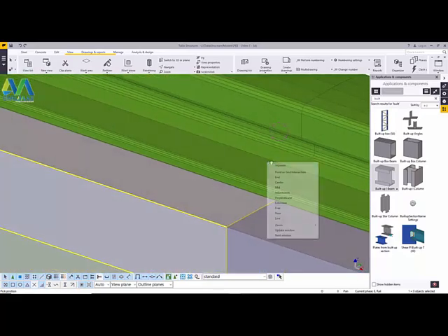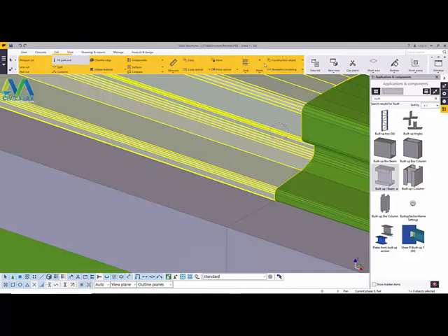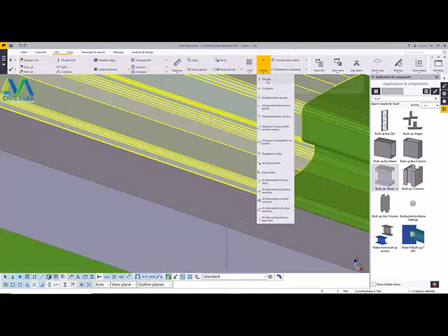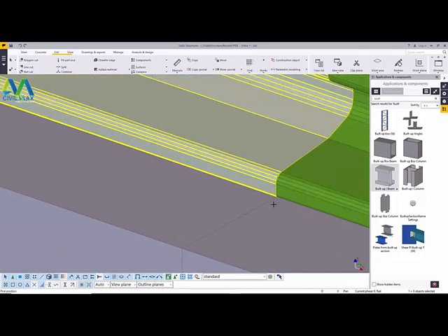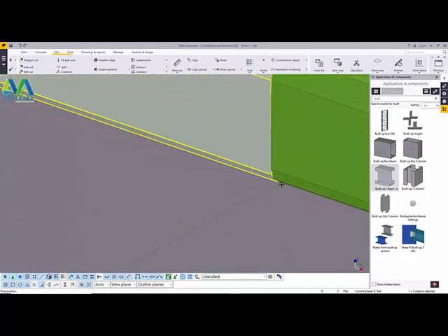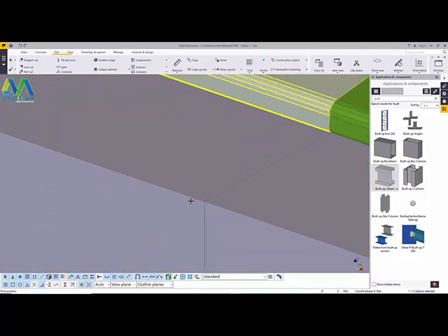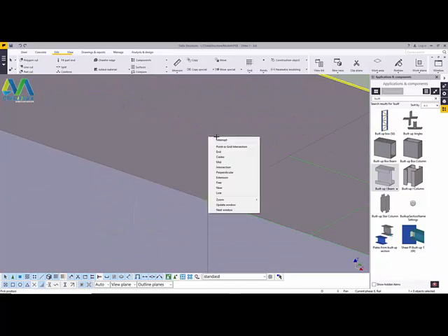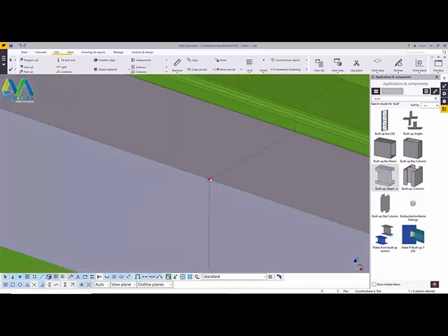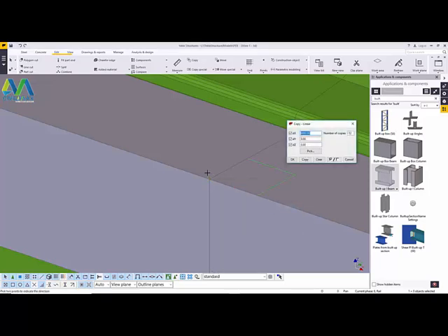So what we are going to do, we'll come to edit here and come to points and come to any position, and we want to locate a point right at the bottom end here, or just place a point here, use OK, and pick on that point, right click and come to special copy and come to x-axis. We'll feed here, give it 80, that's okay, 80 is okay, and click on that.